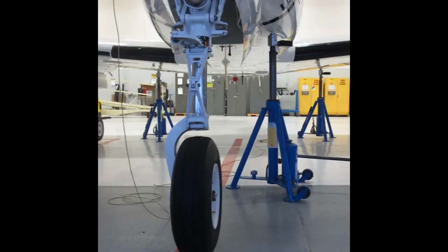Jacking the aircraft. Aircraft are often weighed by rolling them onto ramps in which load cells are embedded. This eliminates the problems associated with jacking the aircraft off the ground. However, many aircraft are weighed by jacking the aircraft up and then lowering them onto scales or load cells. Extra care must be used when raising an aircraft on jacks for weighing.